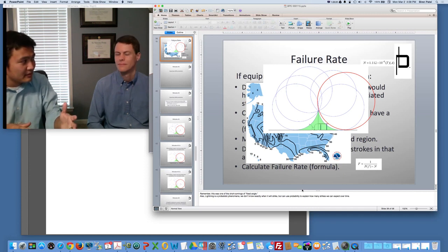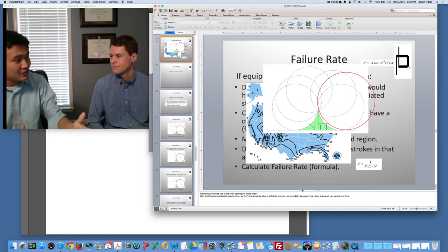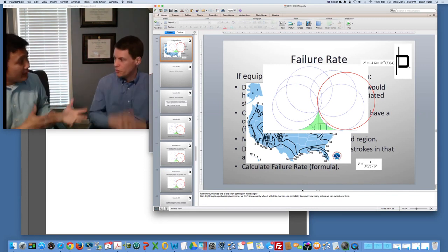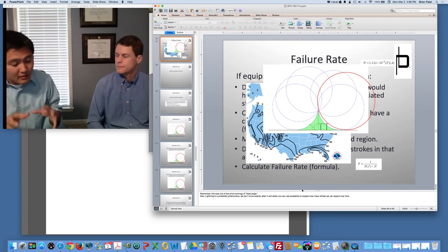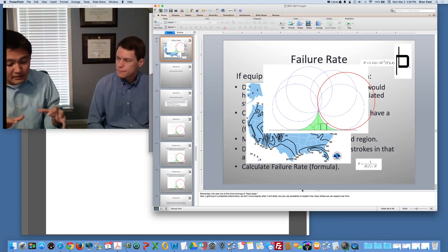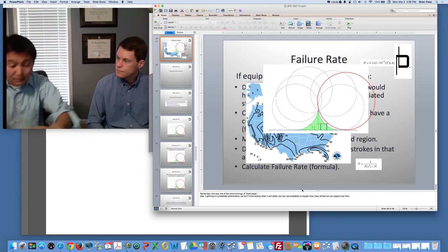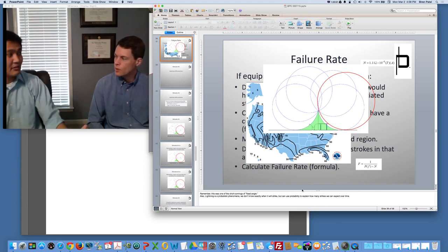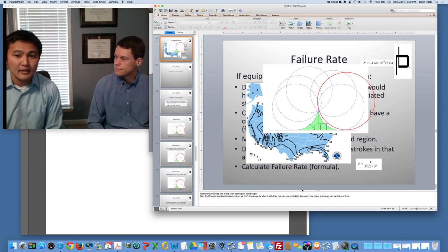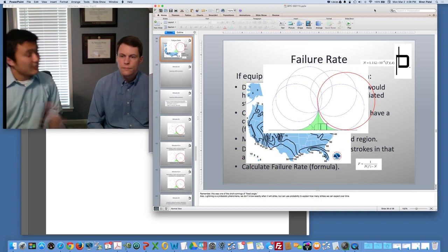So if you have set your failure rate to 1 failure every 100 years, and that substation is going to expand, as soon as you build something else, you've gone over. So you have to plan for the expanded substation from the beginning. Or maybe a better, more practical way of doing it is to set a higher failure rate that has some window, and then every time you expand that substation, you have to reassess the whole station and see what the failure rate is of the whole station. So that's important.